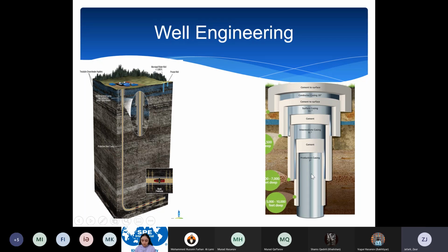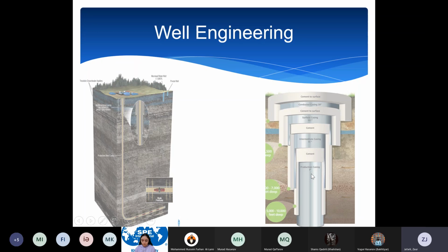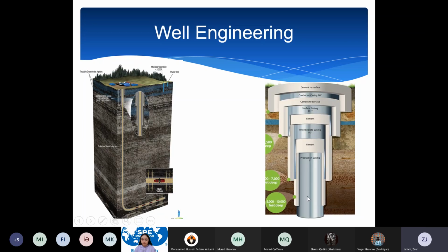The one main rule you need to keep in your mind is that when you drill a well, the design comes from bottom to top. It doesn't come from top to bottom. I mean design-wise, okay? Because when a reservoir engineer or subsurface team decides that they're going to drill to that target, they need a well to that target, and they need to produce a certain amount of hydrocarbon. You have to start from the bottom.